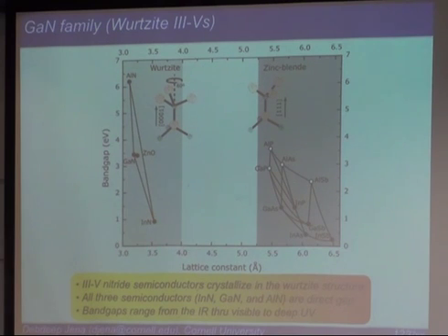So this family is called zinc blende. I think you know that part, right? It's basically the same as the diamond or the silicon structure. It's just that the nearest neighbors are different atoms. It's a compound, right? Gallium and arsenic, or indium and arsenic. So all these are zinc blende, and the crystal structure looks like this. Let's think this is gallium, and the reddish one here is arsenic. If you go up to the next level, essentially this tetrahedron, this atom is right on top of that one, right on top of that one. And then it keeps repeating along this 1-1-1 direction. Does it make sense? So this is gallium arsenide, and the arsenic is, in 3D space, right on top of that along the z-axis.